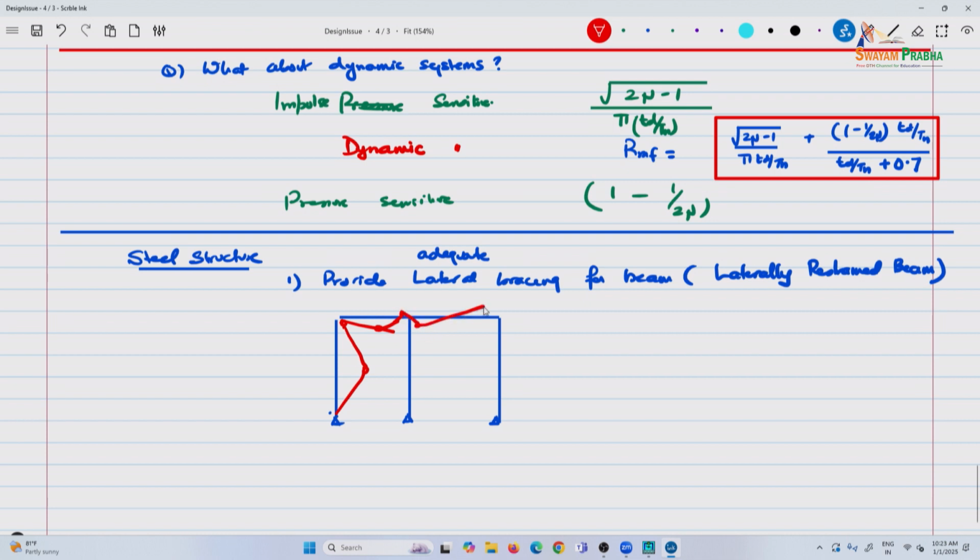So, these are, let us say, the plastic hinge locations. You have to decide, and in the courses you have seen how to come up with plastic hinge mechanisms for steel structures, right, plastic design. So, when you calculate, the theta should be less than 2 degrees.